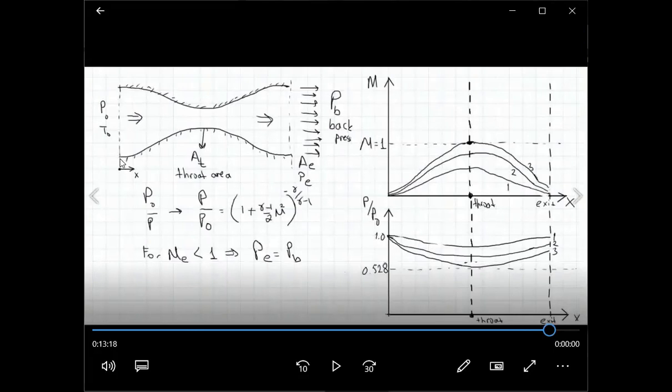We say this left-hand side of the converging-diverging nozzle is connected to a very large chamber in which we have stagnation conditions. Basically, nothing is moving. So our starting point is basically Mach 0. That's why static pressure is equal to stagnation pressure, so it's equal to 1. Okay, hocam, thank you.